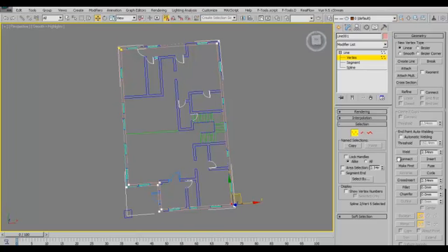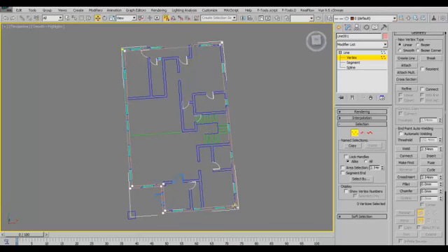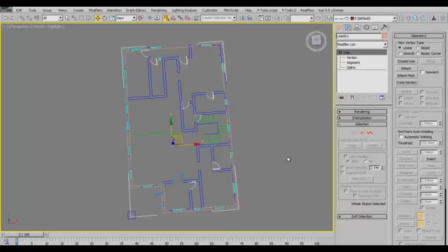If you have multiple yellow spots, like now, let me come to this vertex point and break this part. If I break this, you can see from our spline here that we don't even have one yellow point, which shows that there's somewhere which is not closed.